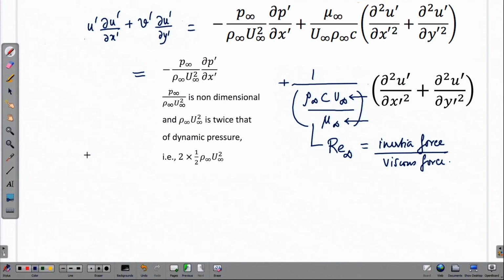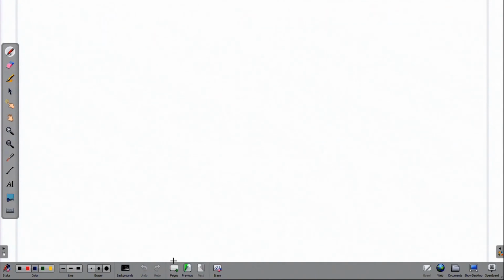But for practical applications, even for fairly large finite values of Reynolds numbers, the viscous effects reduce to a very insignificant level for the overall flow field, and they get confined to a very thin layer around the body. So, most of the flow field behaves in an inviscid manner. So, this is the purview of inviscid flow analysis in aerodynamics. That is where it gains so much importance, because most of the aerodynamic flows are high Reynolds number flows, and therefore, inviscid flow has a dominant role to explain such flows.